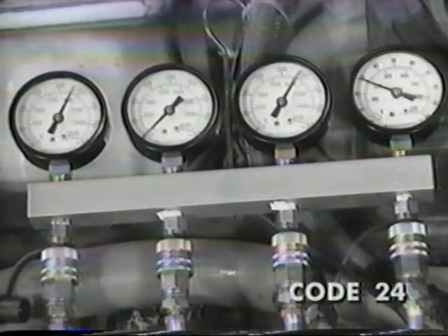Interrupt pressure should be 0. Bypass lockup pressure should be plus or minus 5 psi or 34 kPa of main. And lube pressure should be 15 to 20 psi or 104 to 140 kPa. Again, if any of the pressures are out of spec, replace the hydraulic valve.